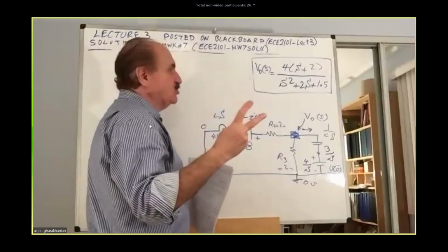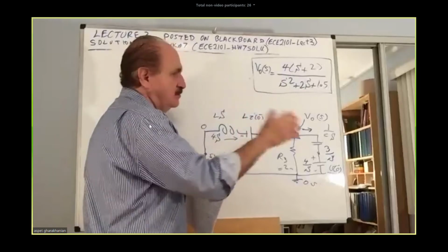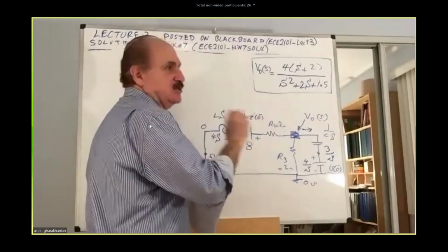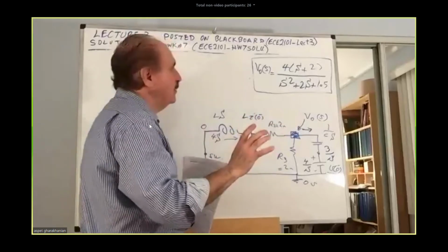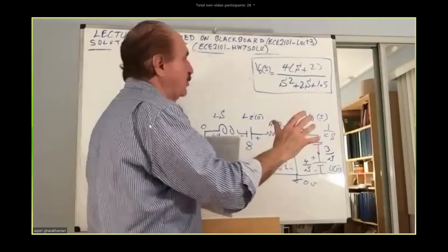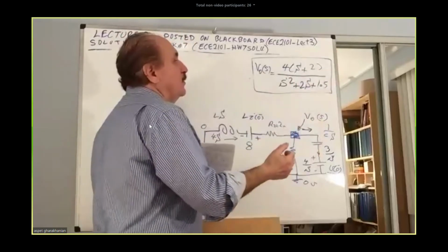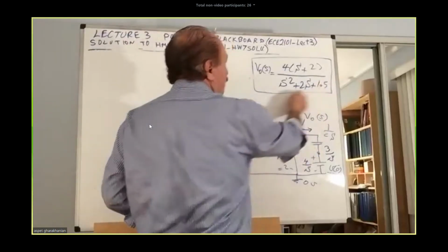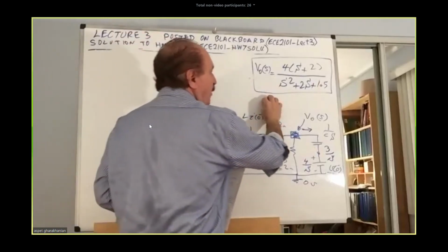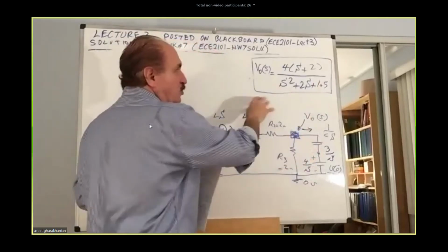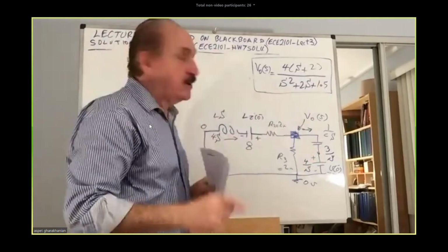The question is this: if the two poles were real, two distinct real values, it would be a piece of cake, the easy case, case one. If the poles were duplicates, like s plus 8 squared, a perfect square, then you have duplicate poles. There is another way of breaking down that function for duplicate poles. In our case, our poles are complex.